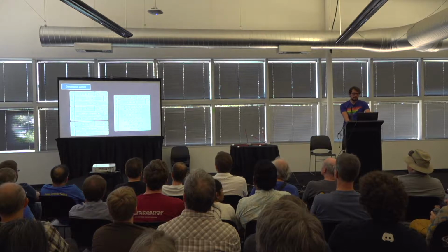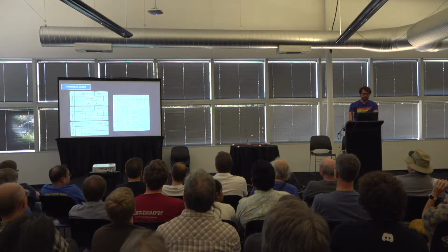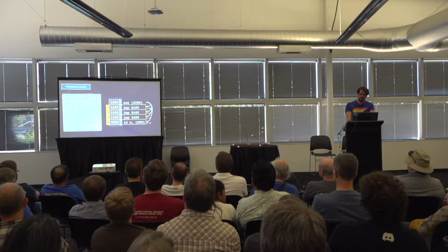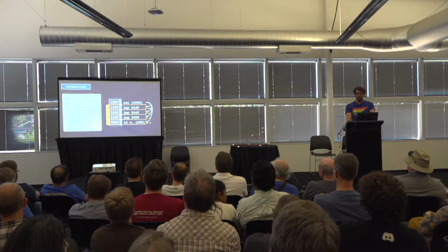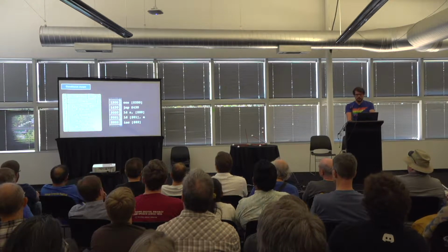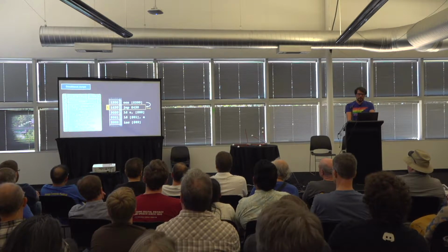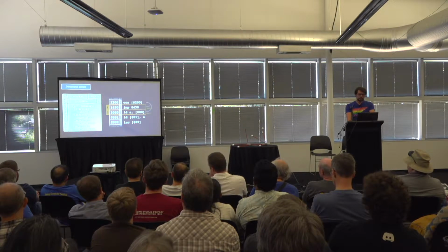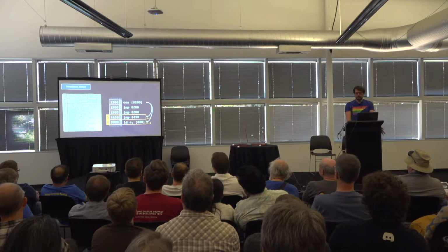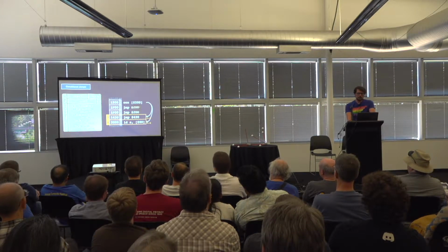CCS, count, compare, and skip, is a 4-way fork for execution. Depending on whether the value in memory is positive, negative, plus 0, or minus 0, it will jump to one of the next 4 instructions. If you know the value is positive or 0, you can ignore the other 2 cases and just fill the first 2 slots. And if it's supposed to be only negative, you have to skip the first 2 slots. They should never be reached, but it's good practice to fill them with error handlers.